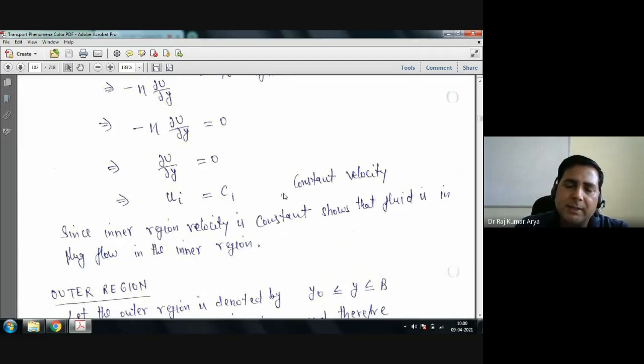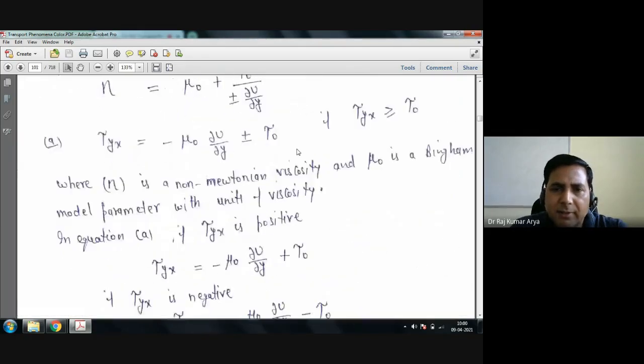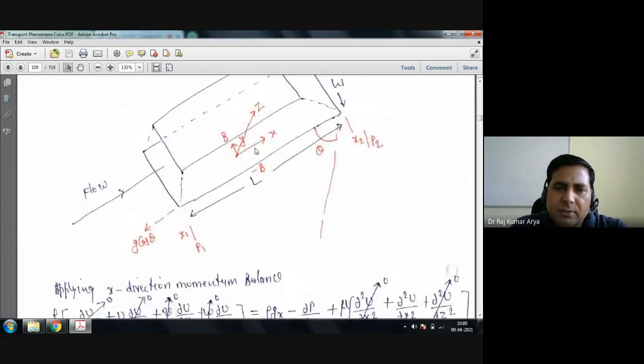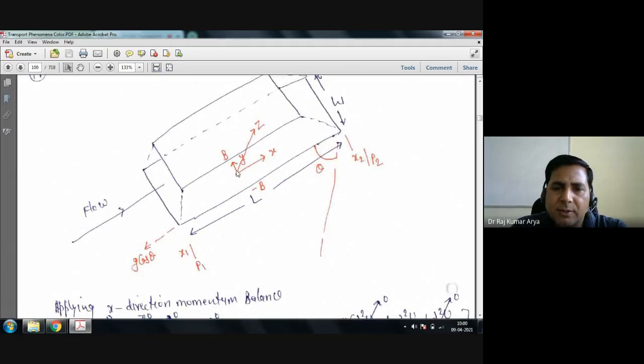Same way after that, as I told in the figure, I can explain here. If you move this distance up to y naught, this velocity will not change. After that, what will happen? The time you reach here, you are going close to the wall. So the wall would create an effect on the flow. As you go close to the wall, which is fixed, your velocity would be 0. From here onwards, your velocity would try to change, right? Keep on decreasing.